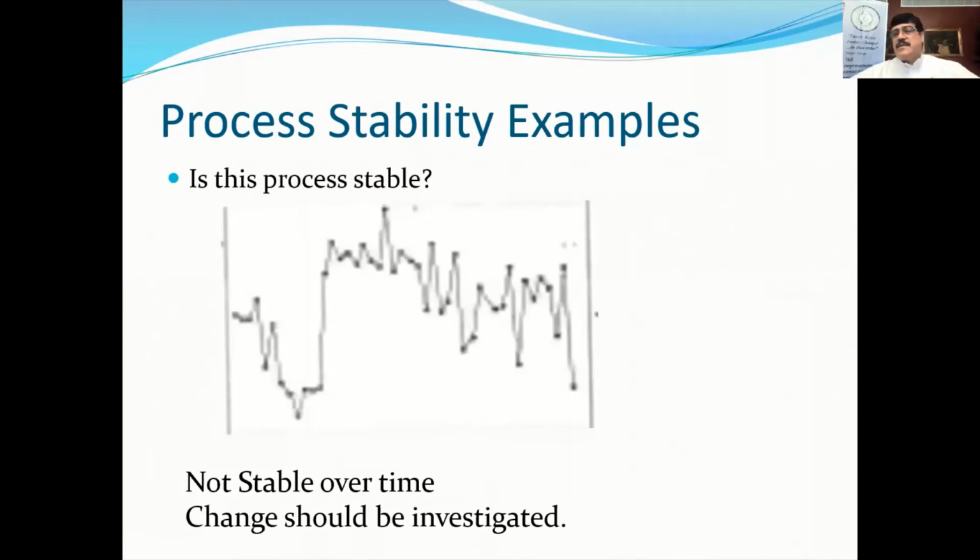Again, all of these tools are not very difficult. Once you understand the concept of them, all you need is to take the data. Normally, you put them in a software, you produce these graphs, you look at the graphs, you look at the analysis that the software will give you, and based on this, you make a decision. Because if you don't look at the data carefully, if you don't examine your measurement system carefully, you can be making big wrong decisions down the road. You think that you have a problem when you don't have a problem, or maybe it's the other way. You don't think there is a problem when there is a problem.